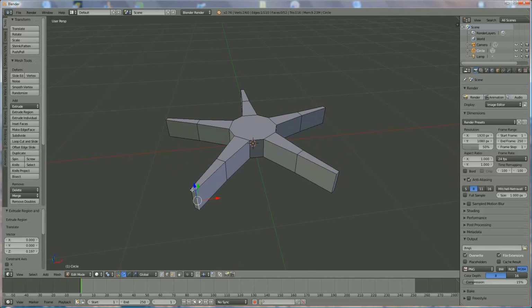Now we select every vertex, one after another, still holding down the Shift button. Release it, and we're going to press S. We're going to switch first of all, escape. Going to switch back again to median point, and we're pressing S, so we bring them to the center, something like that.